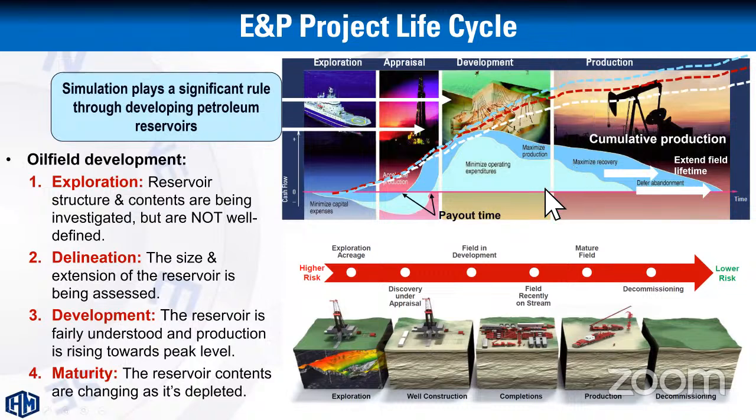So the role of reservoir simulation is typically very important and critical during the appraisal, which means we are collecting more subsurface data to understand the reservoir fluid and rock properties, and also reservoir geometry and reservoir structure. And also it's very critical during the development phase to define several field development plans or several depletion plans to achieve the ultimate economic recovery. This is mostly the main objective of a reservoir simulation study.